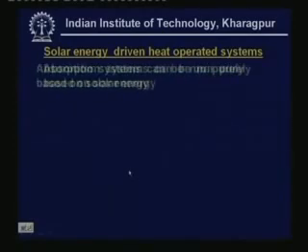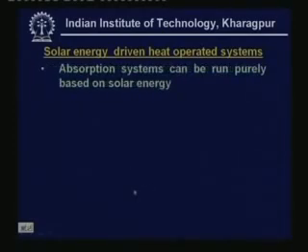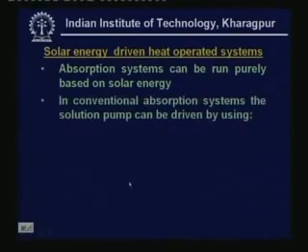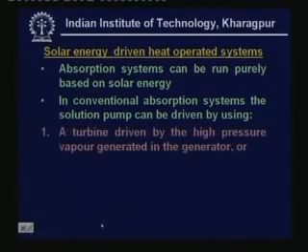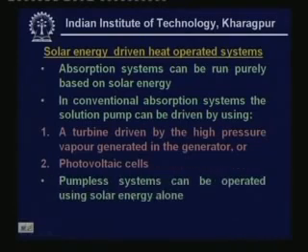And let me very briefly explain solar energy driven systems. I will not explain in detail, but I will just state that absorption systems can also be run purely on solar energy. If you are using a conventional system, then the solution pump, which requires mechanical energy, can be driven using a turbine driven by the high pressure vapor generated in the generator. Or you can use photovoltaic cells and a motor to run the pump. And if you are using a pumpless system, of course you do not require any mechanical energy, and you can operate it purely on solar energy alone.